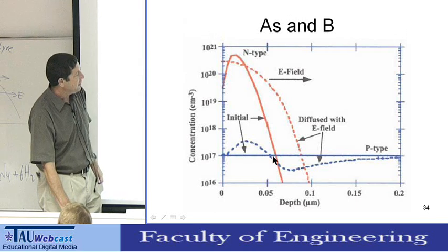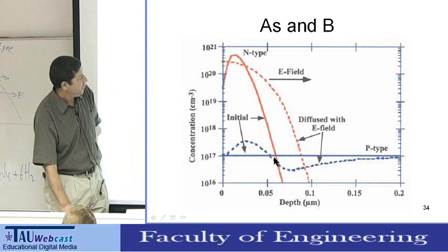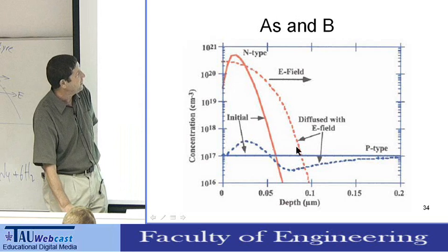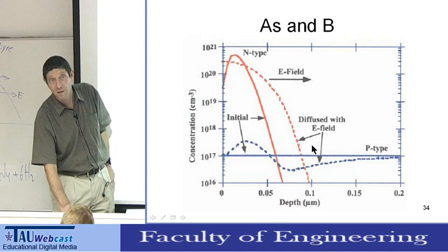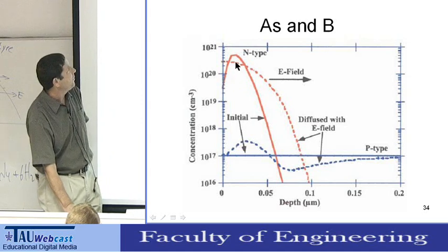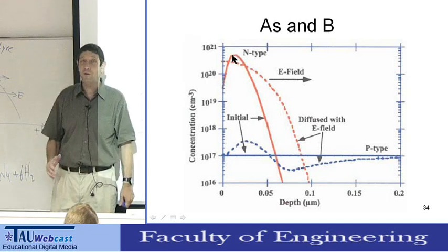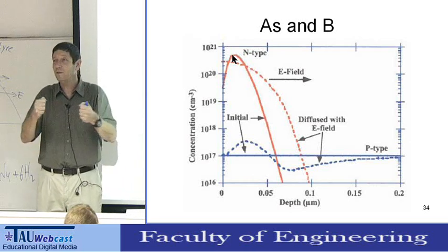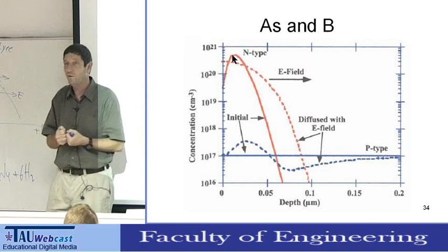And this is typical near junctions. You find a lot of anomalies because near junctions you have areas with high defect density, low defect density, high concentration of vacancies, low concentration of vacancies. Because here you have a lot of dopant, almost 6 times 10 or 5 times 10 to the 20. And because you have a lot of arsenic atoms that generate mechanical stress, they generate more defects near the surface.